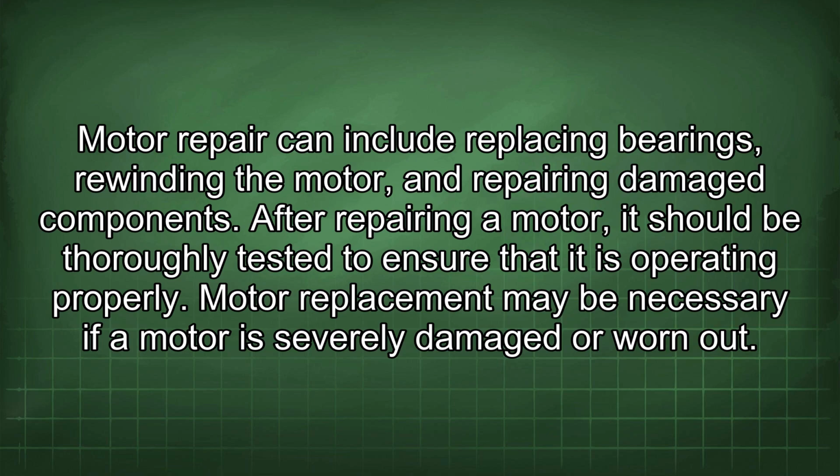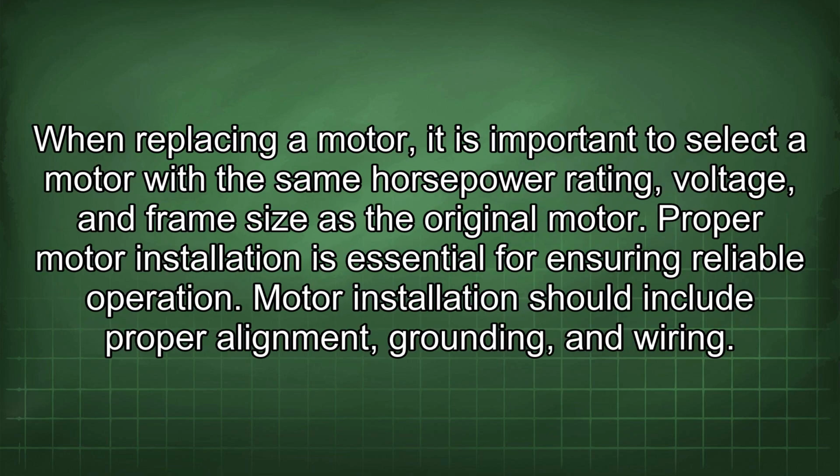Motor replacement may be necessary if a motor is severely damaged or worn out. When replacing a motor, it is important to select a motor with the same horsepower rating, voltage, and frame size as the original motor. Proper motor installation is essential for ensuring reliable operation.